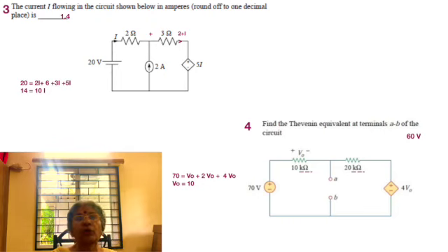What we should recall from our earlier experience is that now A and B are open circuited. So whatever current flows from the sources flows through both the resistors in series, because there is no provision for current to flow through A to B. Since the same current flows through 10 kilo ohms and 20 kilo ohms, if V0 is the voltage across 10 kilo ohms, then the voltage across 20 kilo ohms has to be 2V0.